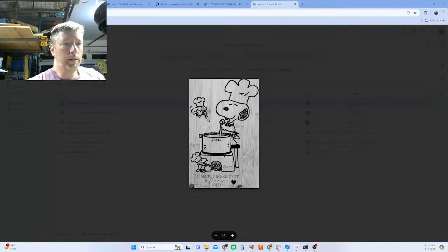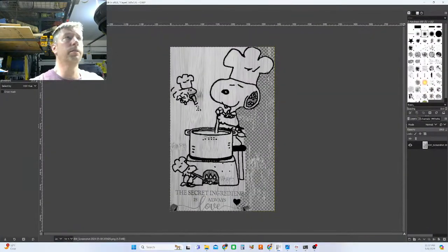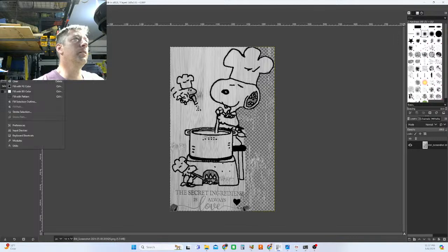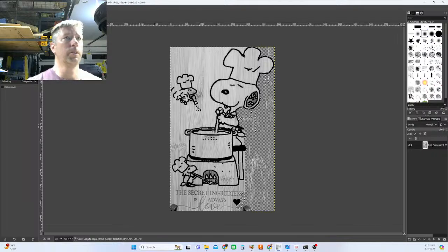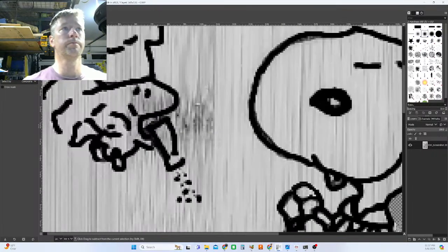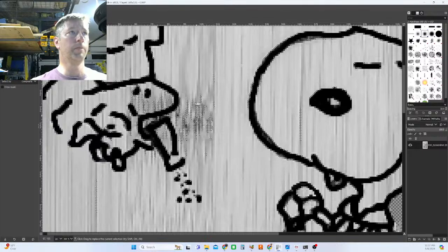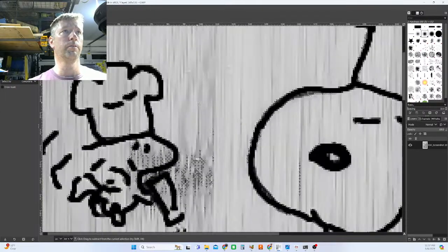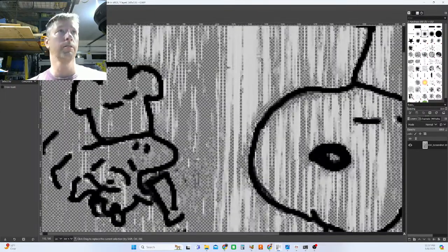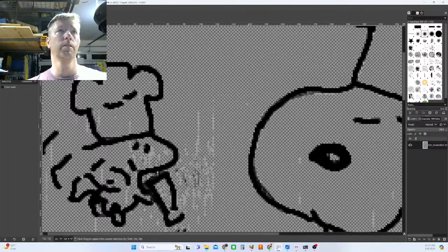There we go. Okay, so we're going to bring this back up here actually. And so what we're going to do is we're going to go to Edit, and we're going to go to Select by Color. Or select, and go down to the Select menu, and we're going to Select by Color. And so Select by Color is when I look at the image itself, and I want to move all of that color of shading across the entire image. I'm going to pop that in, and I'm going to go ahead and delete those. I'm going to select that for pretty much all the colors throughout the spectrum until I get that all set.